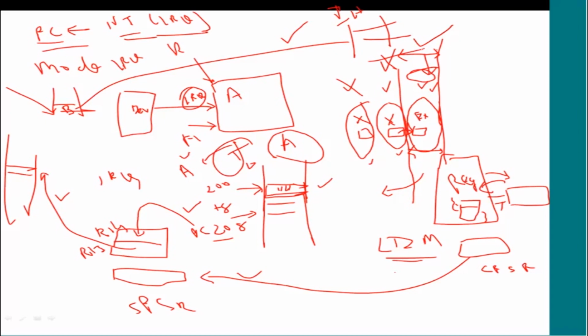So in this case, till this point, a handler has not come, all the job is done. Now what happens after the handler is done? It should come back to the next instruction to be executed. So the handler has to take care of whatever the PC is loaded. It should do -4 so that it comes here, and then it should restore this value into CPSR, and then it should restore the return address, which is here, that will be put into PC, right, -4 will be done into PC, and then starts executing from here.